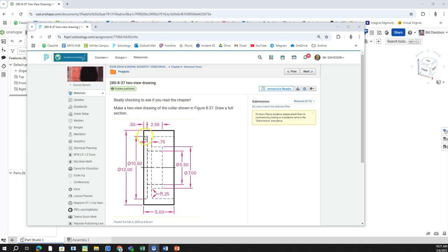So this comes down here, and there's an indentation that goes in 0.5 there. When you see that part right there, that comes in this way. But there's also this right here, which indicates that there's a hole. It's a 5.5 hole through there, and this comes down here. So this area here is evacuated, and it is 7 inches across that right there. So there's like a part that raises up.